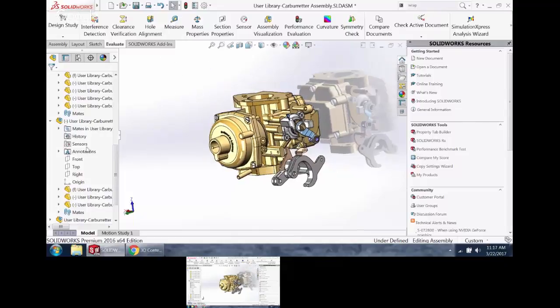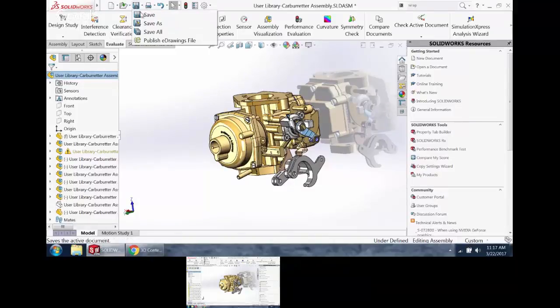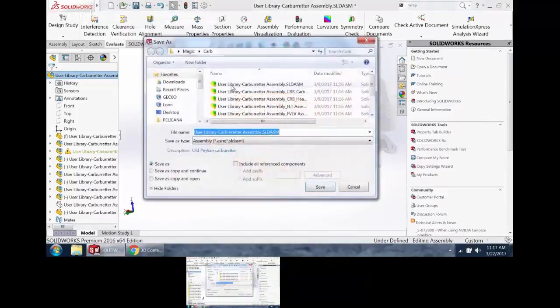Let me make this a little more manageable. I don't want this to come in as a zillion parts. I just want this to be one component in my bill. So when you have PCB boards or assemblies that you're getting from suppliers and you just want to call it out as a single unit, you can save this out as a part. It won't have any type of connection to them, or if you make changes to the assembly, the part doesn't know about that. You need to refresh that part every time you make changes. But it is a nice way to sort of rein in the insanity as far as the hierarchy of the thing. Rather than having dozens of sub-assemblies underneath this thing, it's just going to be a single part.